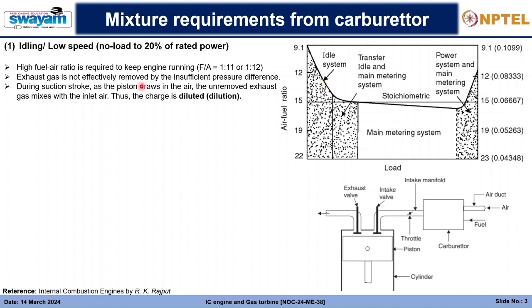The reason behind this is that when idling or low speed conditions are happening, the pressure difference at the cylinder, which is caused due to the burning of the fuel and the ambient, is not sufficient to make the whole of the burnt gases leave through the exhaust valve.